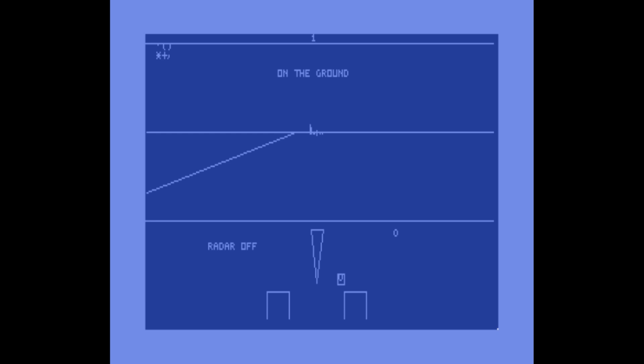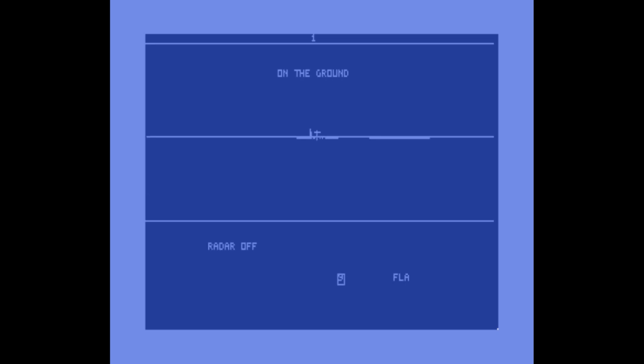So with that, we'll go ahead and turn on the flaps, set the flap angle to 25 degrees, turn up the throttle, and pull back the stick a little bit, and start going. I'll keep pressing enter, aka next here, to keep moving along.